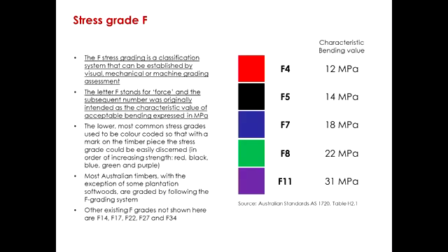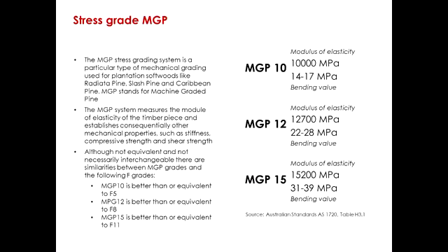All right. And that's the source of the Australian standards in which this sort of stress grading is discussed, the Australian Standard 1720. Each of these, I haven't mentioned it, but it's in the slide. F5, for instance, corresponds to a certain force in terms of megapascals. If we move to machine grading, now the acronym is slightly different: it stands for machine graded pine.